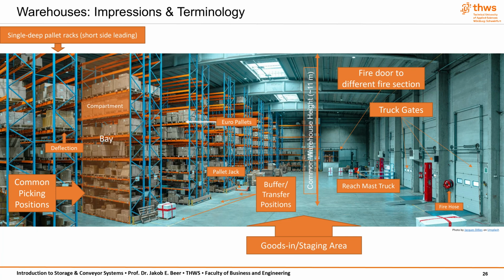Fire safety is another critical consideration. As the height of the warehouse increases, fire protection requirements become more demanding. Most notably, high bay warehouses usually require sprinkler systems capable of delivering water at higher pressures and over greater distances. Installing these systems can be costly, and even when they function properly, they carry a risk of collateral damage. A false activation or a localized system failure can result in water damage to stored goods. In facilities storing electronics, paper products, or consumer goods, this risk is particularly serious.